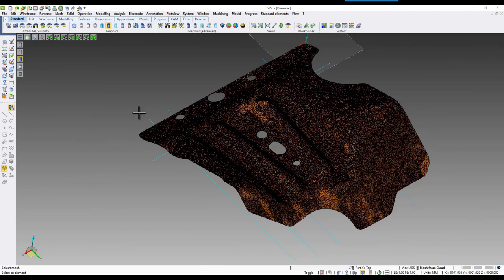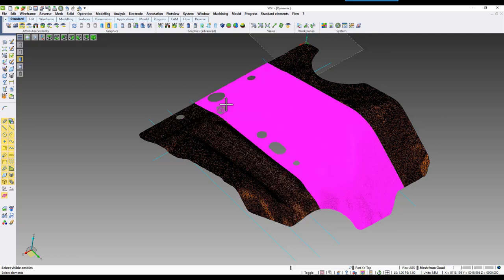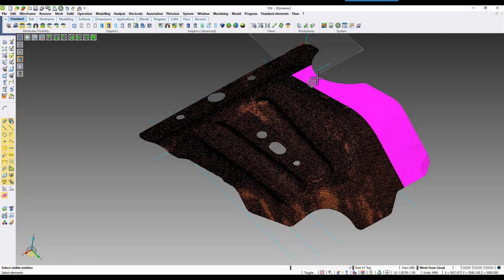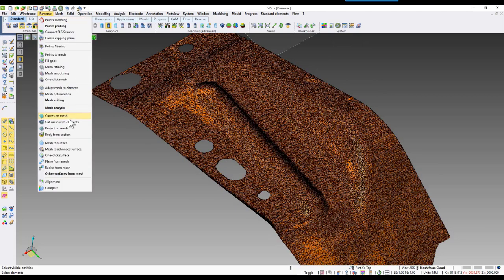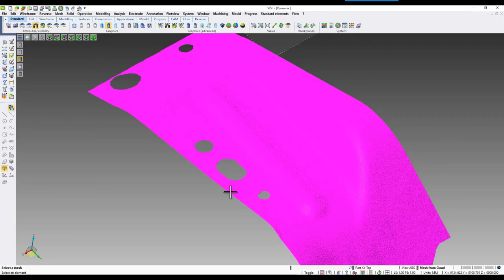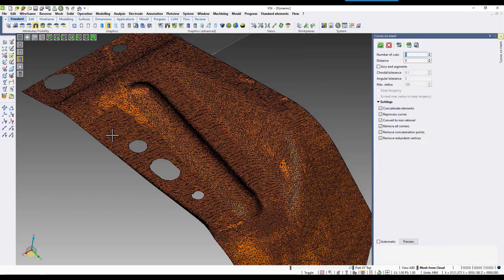As you can see, we're starting to split these meshes in relevance to those elements. So we have our two split meshes in here using the cut body area, and you can make those unique areas just by simply cutting off of the relevant elements that we have in here. So this allows you to draw wireframe or create curves off of those relevant areas to be able to, let's say, create sections off of.